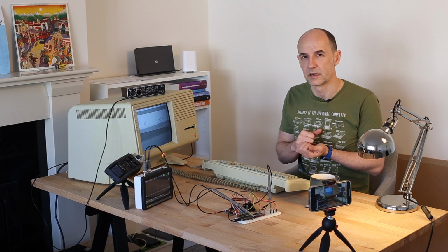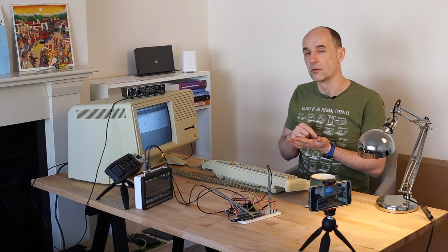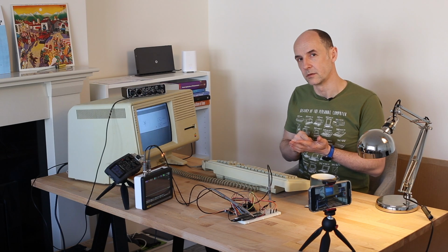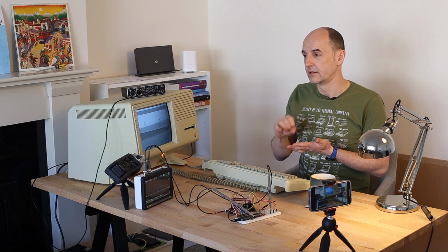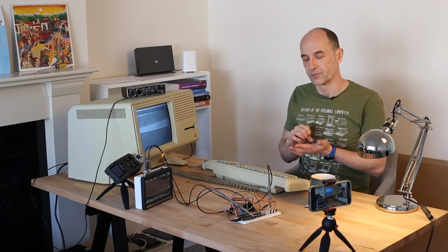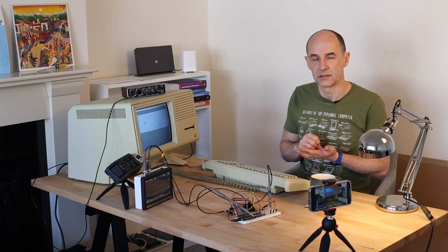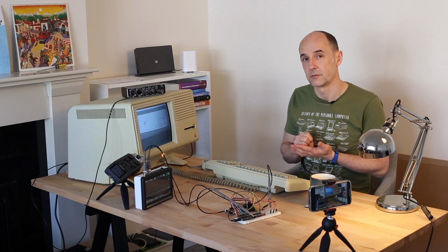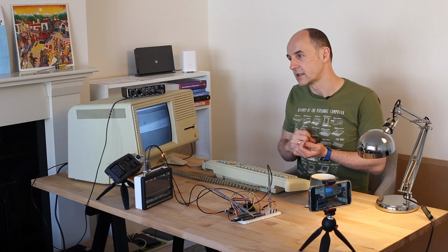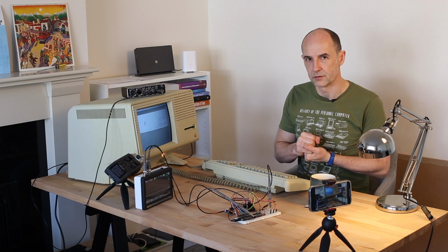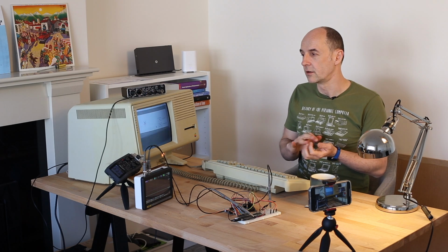There's a signal set on IRQ, one of the IRQ pins, which we can use to know that it has been shifted out, so we can upload something new to the shift register. This way we will control much more than a repetitive pulse train pattern. We can build much more elaborate wave shapes. Especially we can experiment much more with pulse width modulation and achieve polyphony this way, achieve much lower sounds than Apple Lisa is by default able to produce because of this shift register limitation. So there's a lot that can be explored.